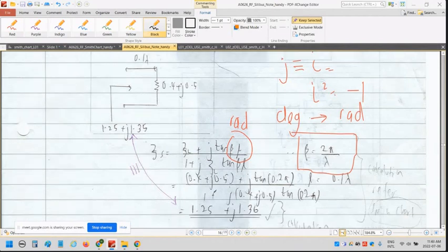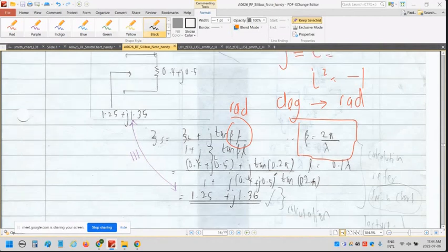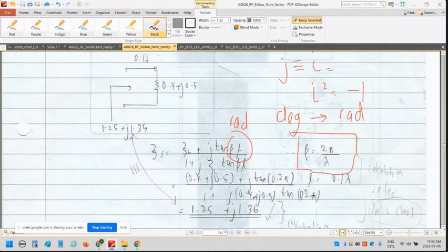And then you divide by 1 plus j ZL. This one is the load, 0.4 plus j0.5. You put 0.5, and for the tangent, same, beta L, where beta L is 0.2 pi. Then take out your calculator, you should get 1.25 plus j1.35. Do it now, and if you get the same answer, show that you understand. Take out your calculator.